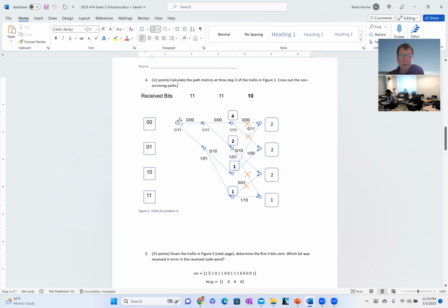So over here, we assume that we start the decoding process in a state of 0-0, right? So we're not accounting for transitioning from any of these other states. It's not until we get to this location here, where to arrive at this state, we could have gotten here from 2 different directions, right? And so our job is to try to predict the most likely direction that we came from, right?